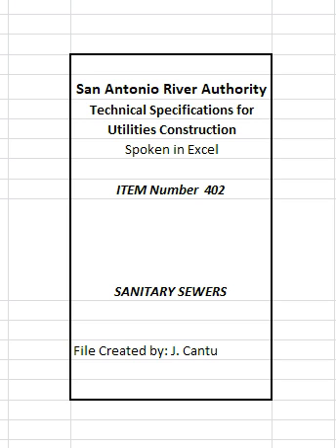G. Watertight testing, 24 hours. All interceptors shall be water tested at job site after being installed, plug both ends and fill to top of interceptor. Interceptor shall show no leakage from section seams, pinholes, or other imperfections. Any leakage is cause for rejection. When leakage occurs, additional water testing shall be made. After correcting measures, test reports shall show total number of interceptors tested. When leakage occurs, corrective measures taken shall be reported by the SARA inspectors. SARA inspectors shall record in daily log with project name, date it was tested and completed.